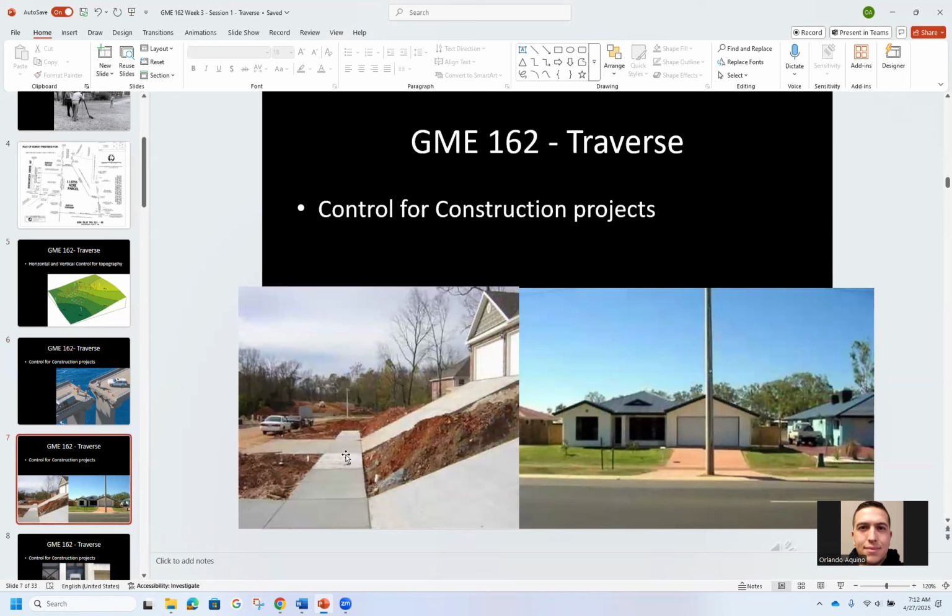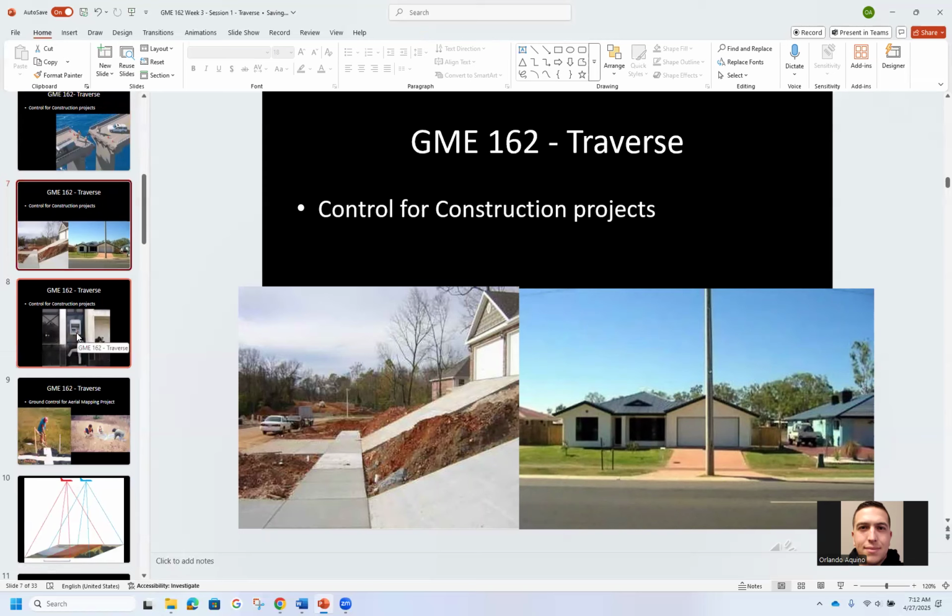Again, another mishap of not getting good vertical data for a house. And you see the driveway run, that is not legal whatsoever. Again, same thing, not knowing where the location of utilities are going to be compared to the actual layout of the houses, of the lots. That's not the best.